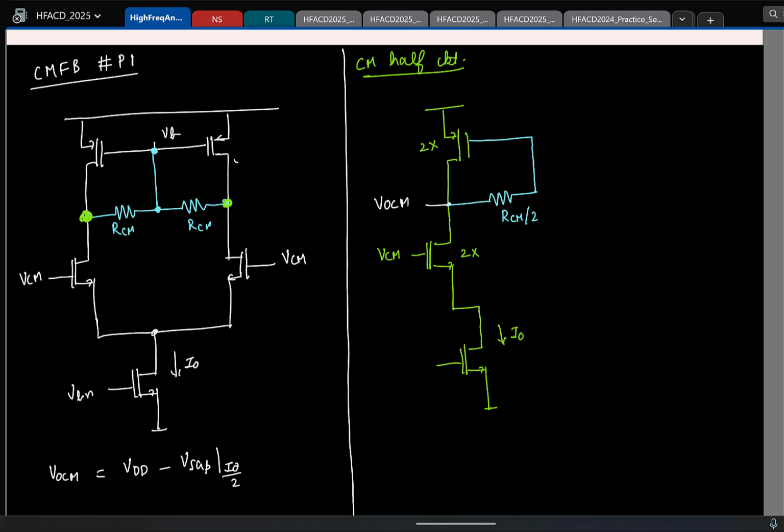Now on top of it, let us say here I have a small signal VIC getting added. Now we can use your small signal analysis and find it, and this is something you might have calculated multiple times. So you can find the small signal common mode gain. I'll give it as an exercise for you to work out. And ideally the common mode gain, you want it to be very small or very large? Very small, right? And you can work out and see it will be small.